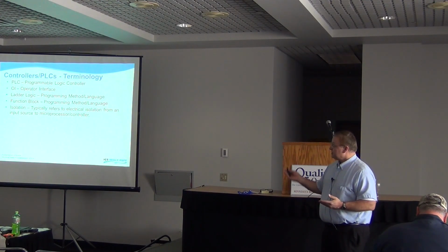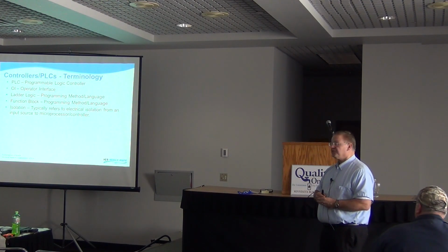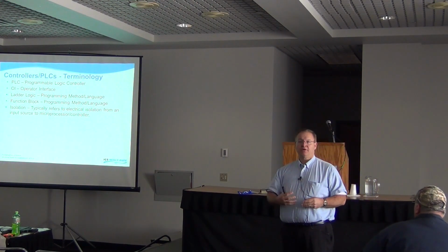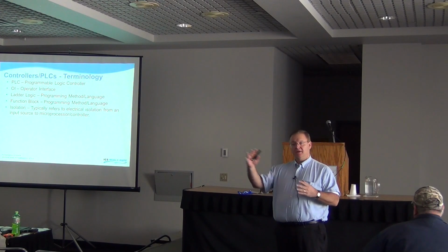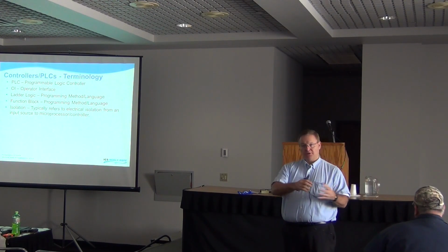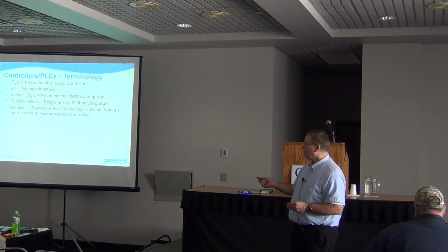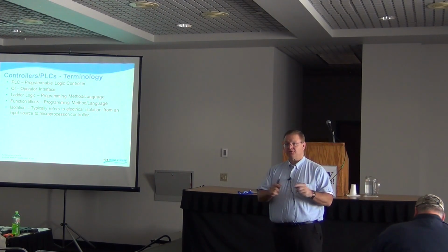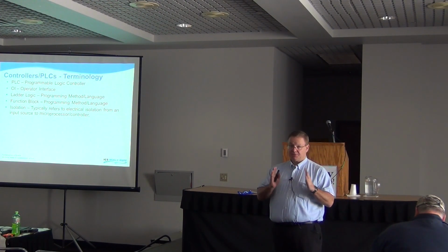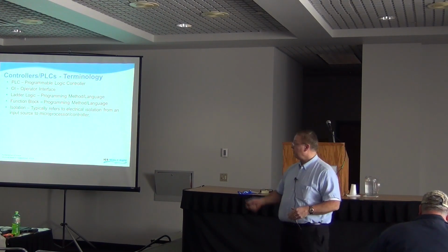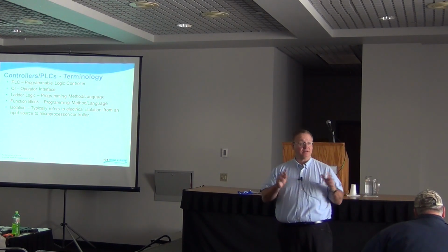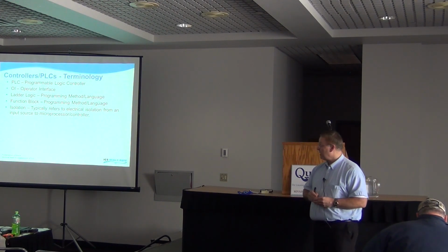Some terminology: PLCs, OI. Most PLCs don't have an operator interface built into them. They need another panel there that's connected to the PLC that can actually be kind of the window into the system. The operator interface is typically not the controller. The PLC is the controller. The operator interface is simply a window into it. And you have to create a communications network between the PLC and the operator interface in order to share and see that data and bring that in.